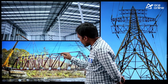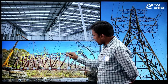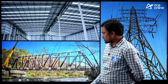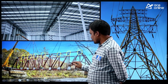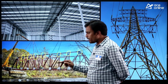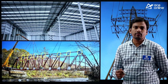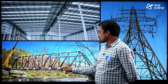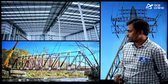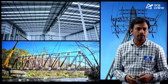At each and every joint there is one white color plate, right? And this plate is known as a gusset plate. So in trusses at each and every joint, a number of members are connected to this plate. The gusset plate will accommodate the members at the particular joint. Clear? This is the first condition. It means all joints are pin joints in the case of a pin jointed frame.